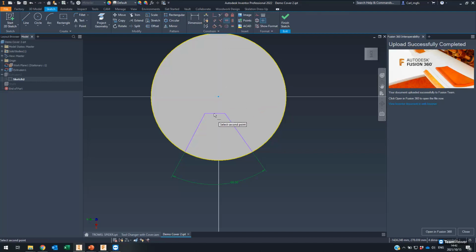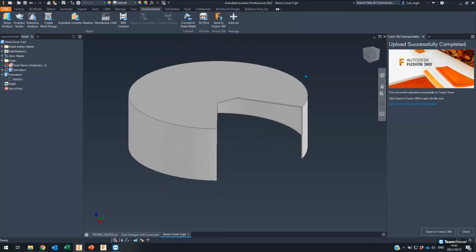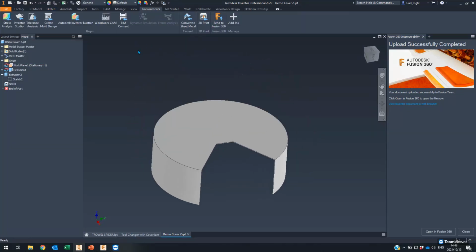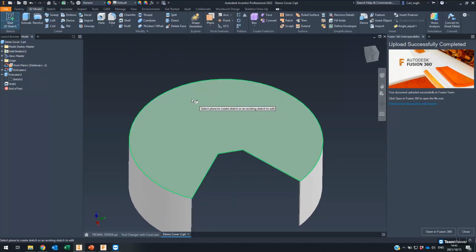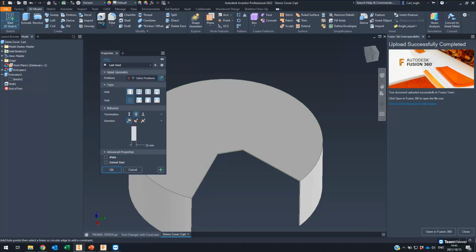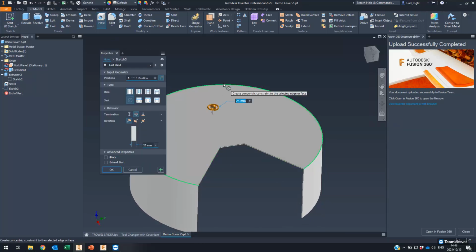And let me just add some constraints here to constrain this a little bit better. So I'll make the change. I'm going to make this 70 degrees, so it's quite a bit bigger. And add a dimension to the back here, 60. Finish sketch on that, so that's slightly wider. And let's make one more sort of more obvious change to this and put a nice big hole through the center at the top here.